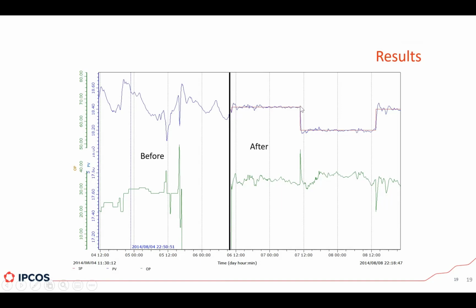You can see that whenever you make a set point change in the pressure, the output of the controller first quickly jumps up and then comes back down to pretty much the same place where it was before. It is the case. The guided vanes are at the same position, so the amount of vapors that you're compressing are exactly the same. You're not changing that. But what you're doing is very quickly trying to condense them faster, so then your pressure decreases, and then once you manage to make your pressure decrease, then you go back to the original point, because the amount of vapors didn't change, so you need to still condense the same amount.